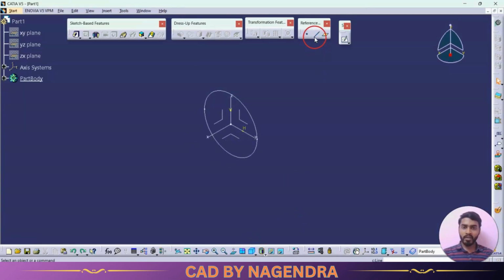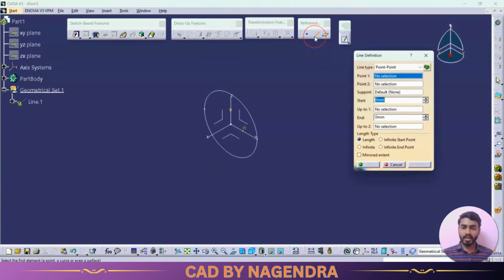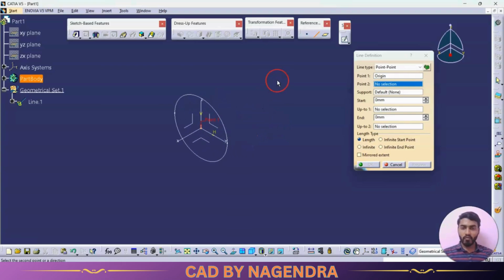Next we are having here 3D line. Just I'll click on line. Line also we are able to create in different ways, by using point to point. Now for example first point is this origin point. One more point we are having somewhere. So if you want to add one line between 2 points, we can use point to point.